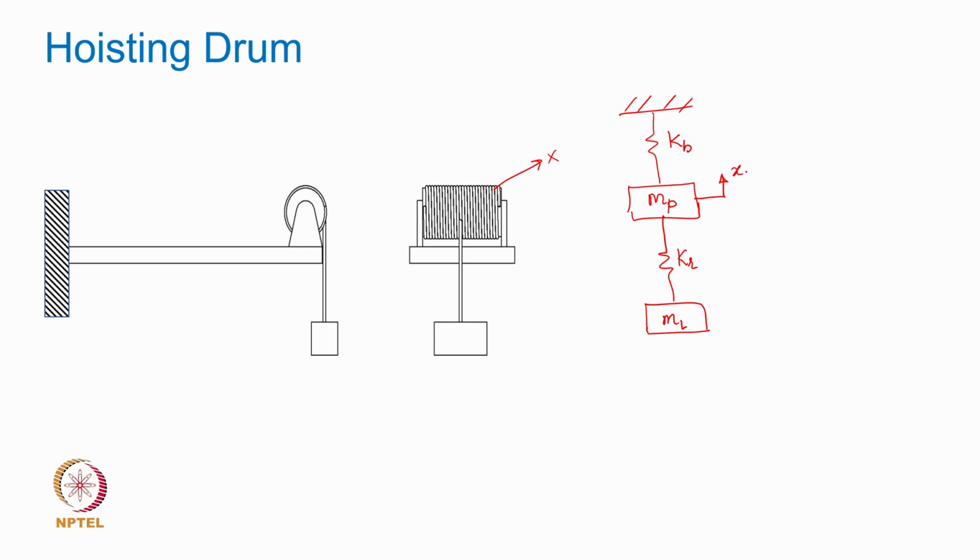One degree of freedom here may be x1(t), with which this end of the beam is going to move. And then I have another independent degree of freedom with which the load, if perturbed, will move. Because they are connected by this compliant element, they can move independently; they cannot be constrained to move together.